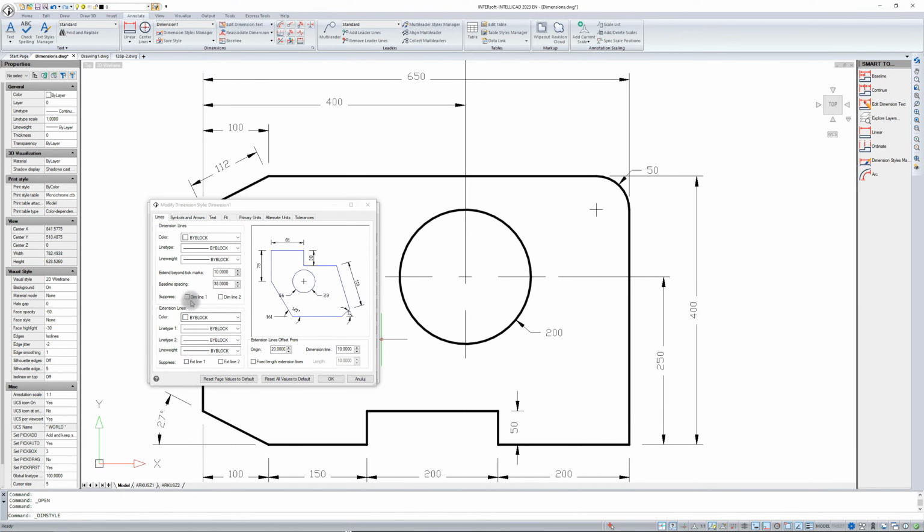Extension lines are those lines that come from your dimension element to the dimension line, extending beyond the tick marks. This is the line that extends the dimension line behind the dimension and possibly in front of the dimension. If the symbol at the end is, for example, a tick mark, full arrowheads close the dimensioning, and then the program does not show this line. If there would be a tick mark, then this line will show and you will have to define its thickness.